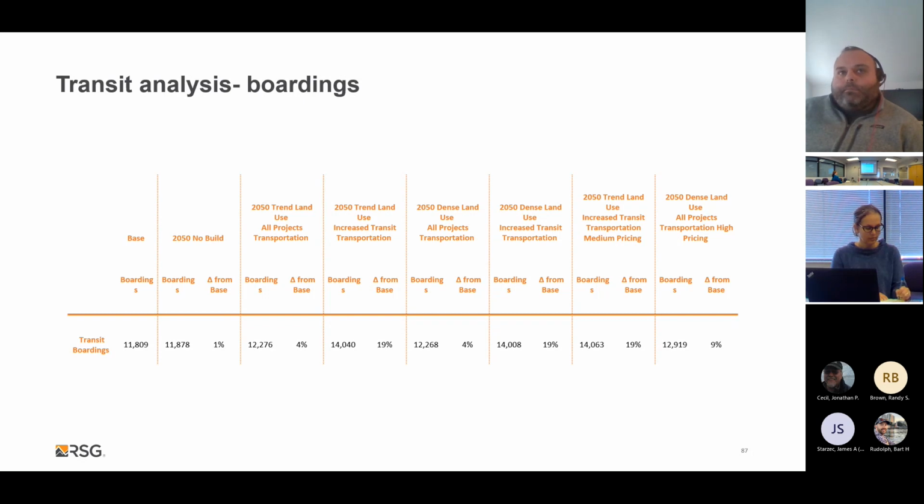Can you describe the difference, or the pros and cons, of a route level calibration versus just the on-off boarding calibration? Yeah, if you did a route level calibration, then you can actually get into more transit planning work on a route level. And so there's additional work that you need to do in order to get to more route level type of transit planning. And then you generally need to have more onboard survey data collected, and then the model can be calibrated to those onboard survey conditions. And then you can start looking at things like adjusting or playing with different parameters that might affect transit usage and doing more robust transit planning activities using the model.